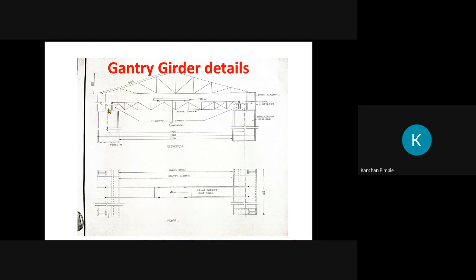So this size is ISMB 100. Then I show this dotted line, which is nothing but the gantry girder. Okay. This one is a top last column. And in that, we observe this rectangular part is known as crane girder with trolley. Okay, and here you have to show the clear distance, where the gantry girder span is. And what is this distance? This is the distance between two columns, nothing but the spacing of truss.